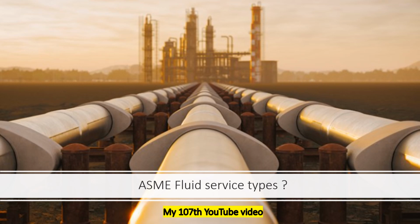The reason is they have categorized the fluids as per the pressure, the temperature, the toxicity, and based on that, the inspection level goes higher and higher. So that if a fluid is more toxic, we can check the line through which the fluid will flow, and the inspection can be more strict, okay, in order to save lives. Okay, so let's start. What are the types of ASME fluid service types, and we'll know briefly about that.